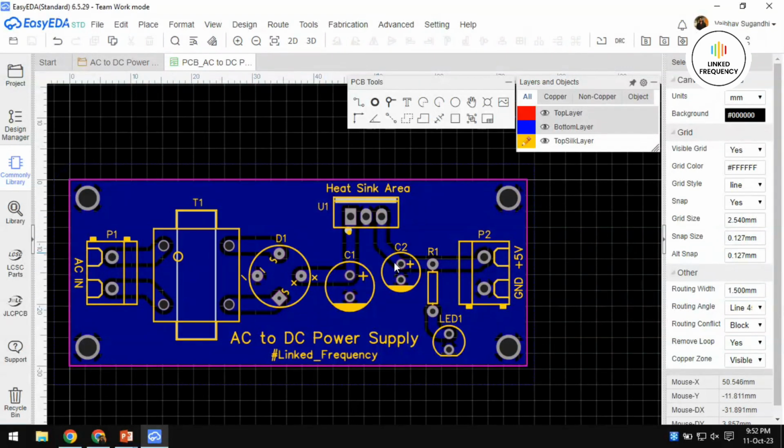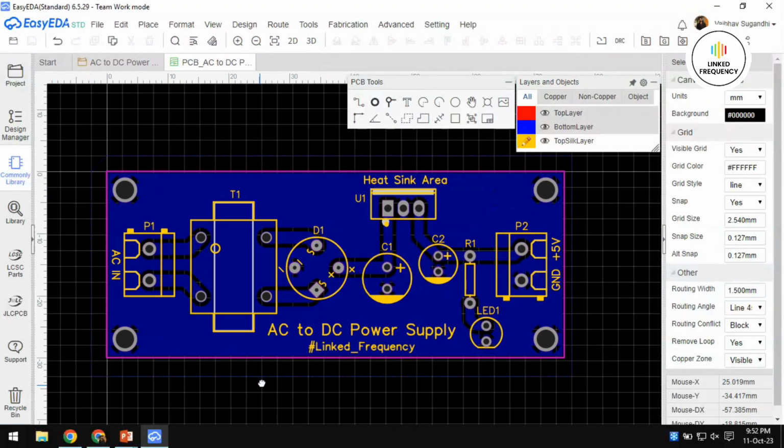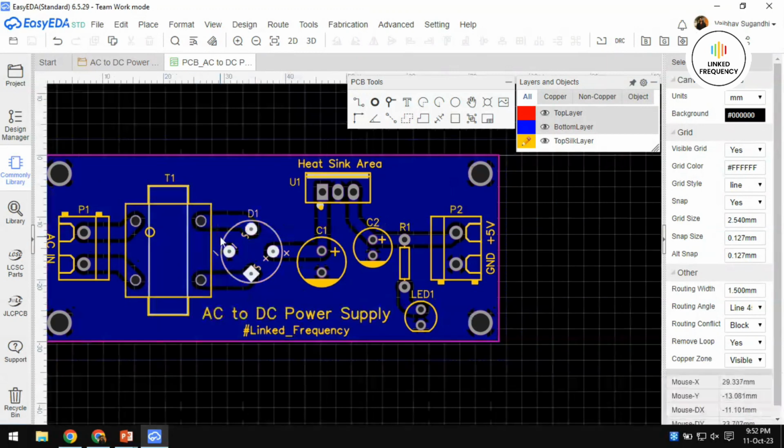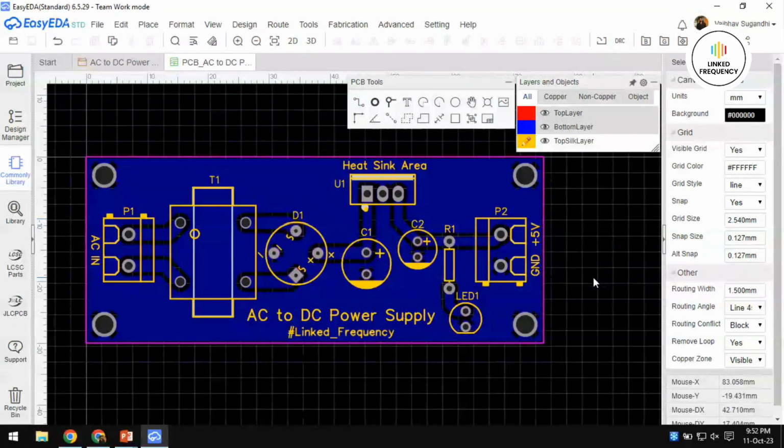And the designator alignment is also a fundamental one, and adding the mounting hole is also a fundamental one. I hope you have noticed in the process of designing this one, my board outline was not as expected as when I started the PCB designing. As per the completion of the step-by-step approach, I discovered that I have to adjust the board outline accordingly. That is how the PCB designing goes if the constraints are not given.